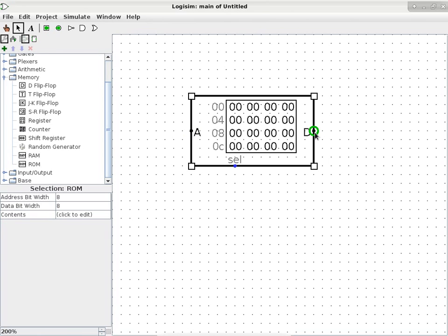And this is the interface to do that. It's the data port. It specifies the value loaded from memory, loaded from this chip. The third interface, which is select, is basically an on-off, because we would like chips to be hooked up in a bus configuration, which means we'll have parallel chips connected to the memory bus. They're all connected in the same way.